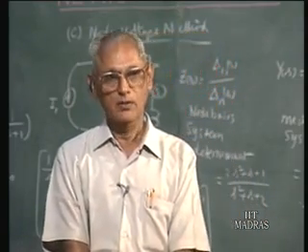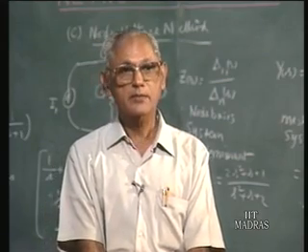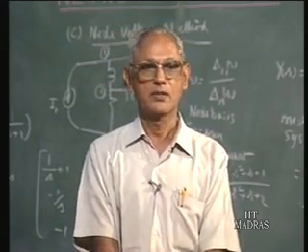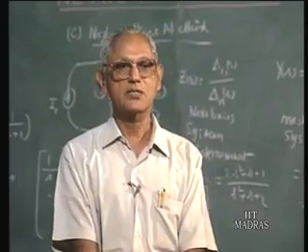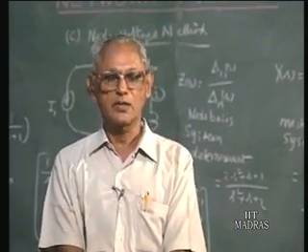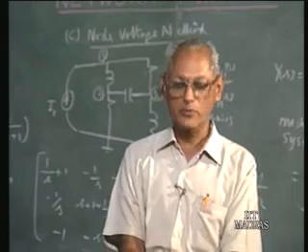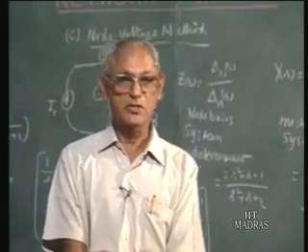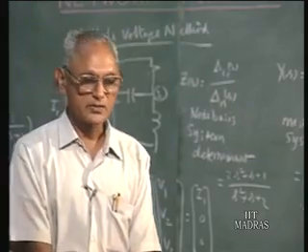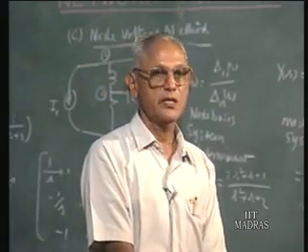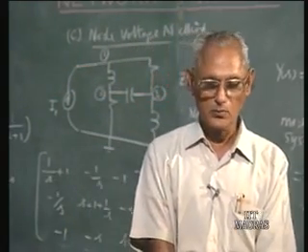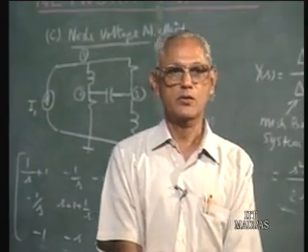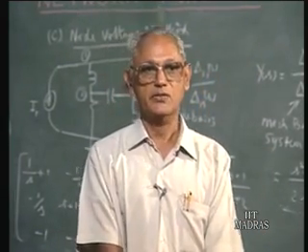Then we looked at the various ways in which we can calculate these impedance functions. I said the entire set of techniques available for calculating the effective resistance of a resistive network in the case of DC can be used here, except that we deal with generalized impedances rather than pure resistances, so functions of s are associated with each term. We can use the series parallel reduction technique, the star delta conversion technique, or more generally the loop current method or node voltage method of analysis. We worked out one or two examples to illustrate the application of these techniques.